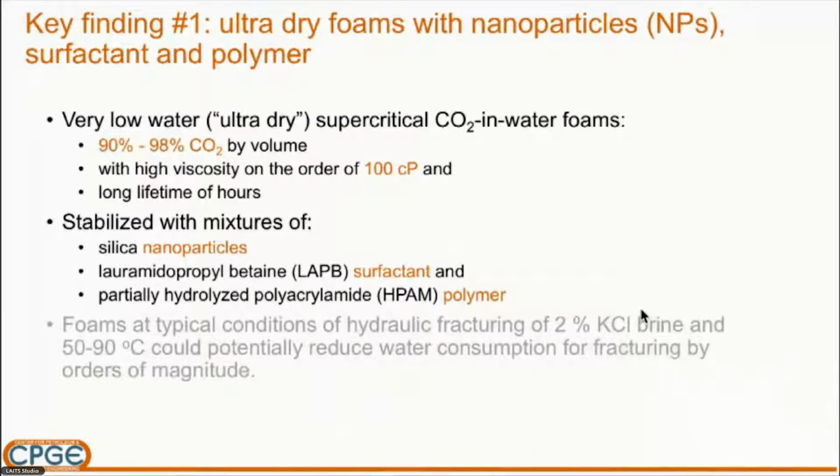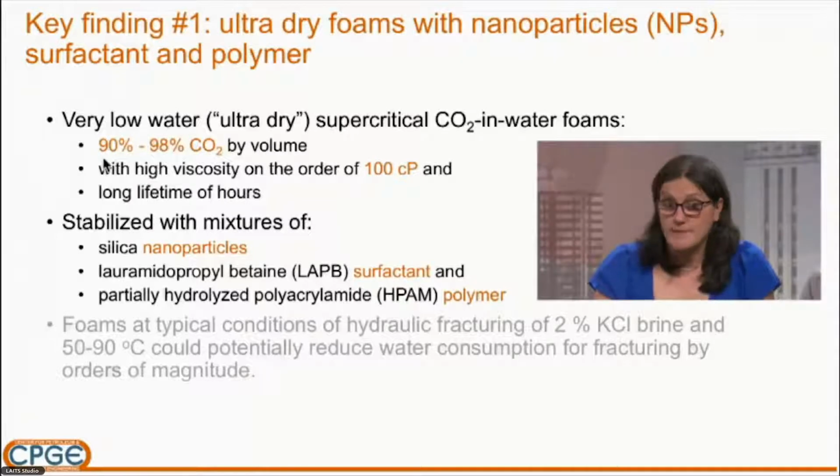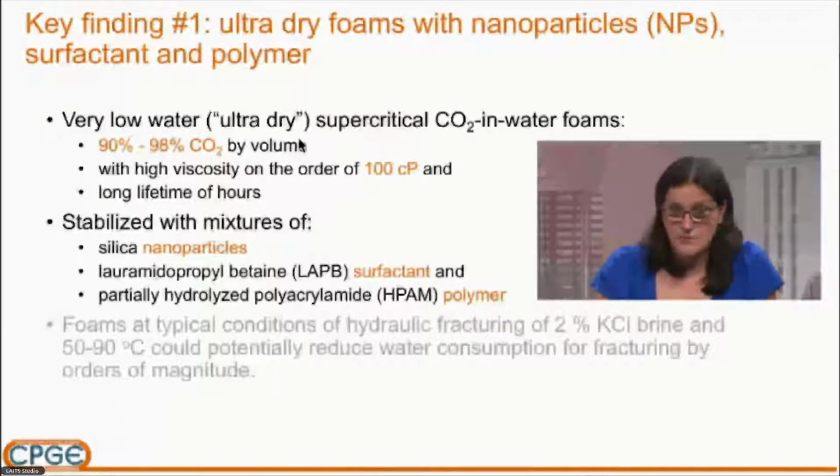So our first generation or our first finding are ultra dry foams with a synergy of nanoparticles, which I'm going to refer to as NPs, surfactant and polymer. We did achieve stability of very high gas quality foams, basically 90 to 98% of CO2 by volume.